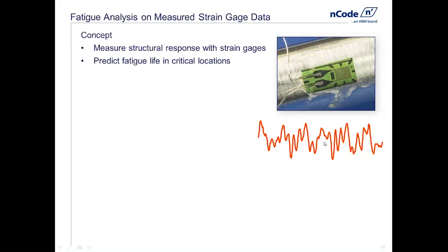We could use it to look at, if we're worried about overloads, how high that peak stress is relative to a fatigue strength or a material strength characteristic, say yield strength or tensile strength. That would help us understand the overload failure criteria. Now, in a fatigue sense, though, we'd want to go through all the stuff we just talked about, which is counting cycles and so on, and do that fatigue analysis for those critical locations.